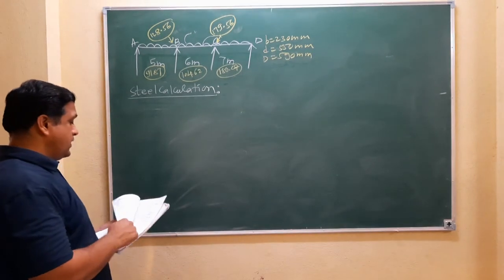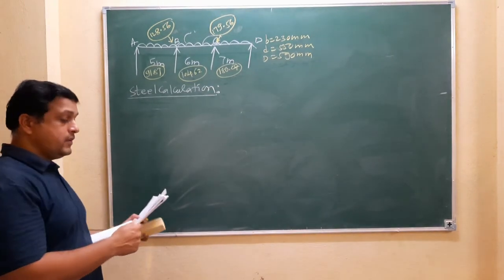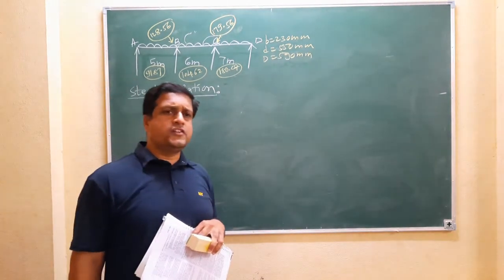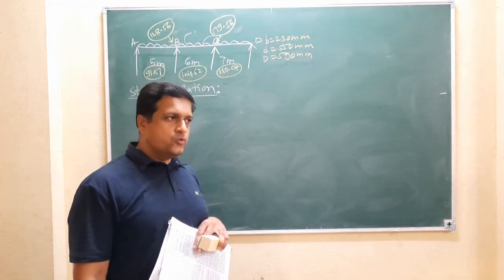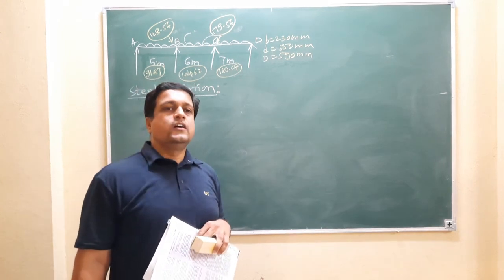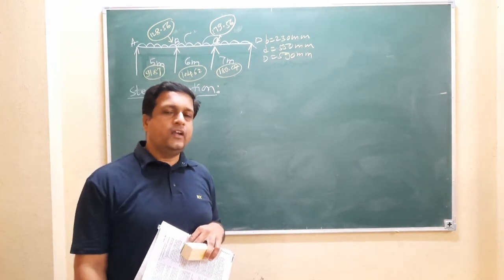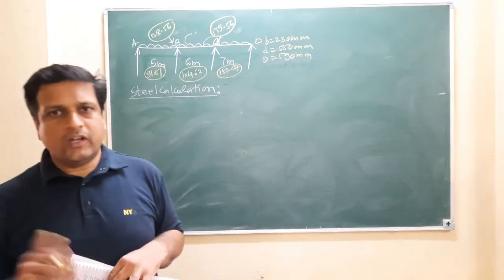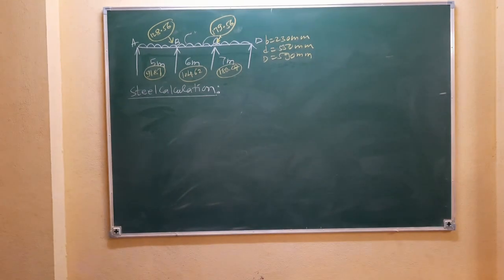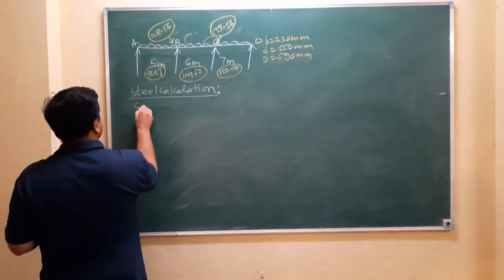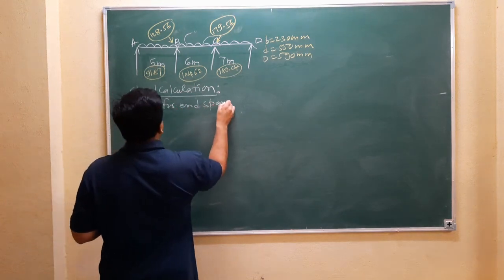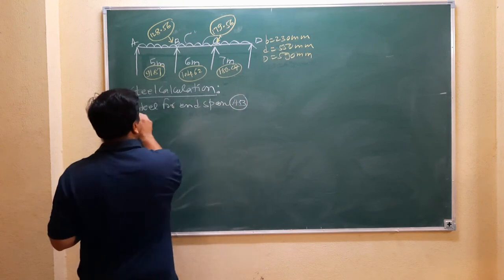So now I want to find out the steel. We have provided the depth of the section for maximum bending moment. So at these 5 locations, the beam is acting as an under-reinforced section. You have to use that under root formula to find out the steel. It is a simple procedure, whatever we have adopted in the last two problems. So first is steel for end span AB.